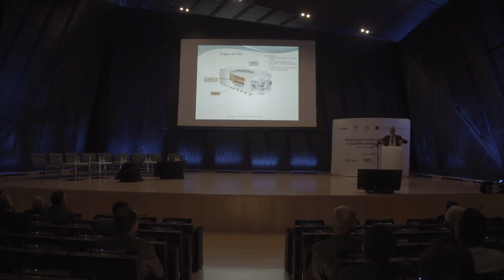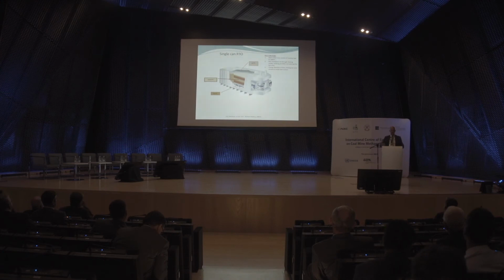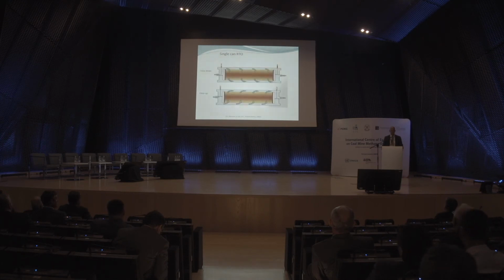So as the air continues through the box, it will heat exchange, leave the heat behind, and then out into the atmosphere. So you pick up heat coming in, oxidize, leave heat going out. So you're slowly moving the heat zone in the direction of the flow. Therefore you change the direction of flow every few minutes, and you have the hot, oxidizing zone going back and forth a little bit in the center. There's no catalyst because this is the natural oxidation temperature of methane.